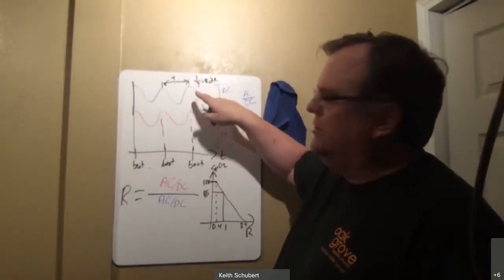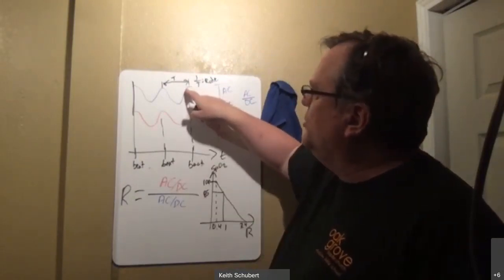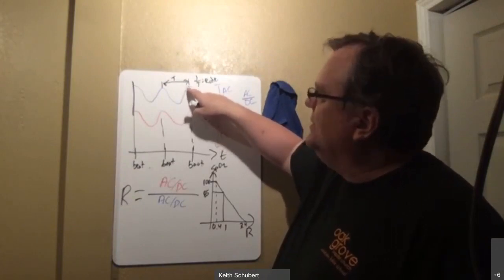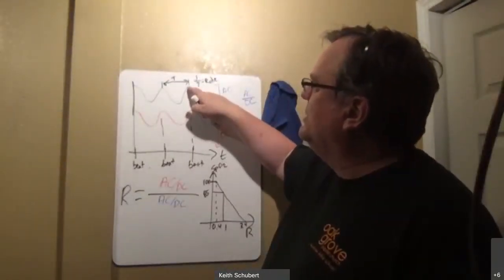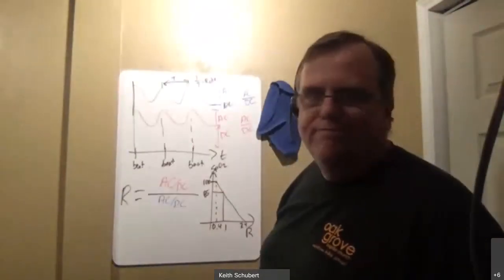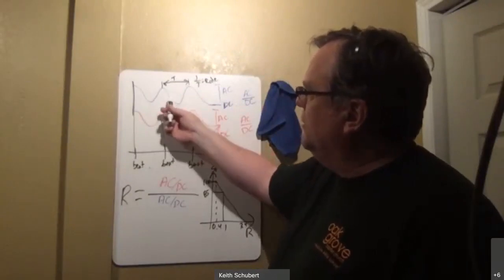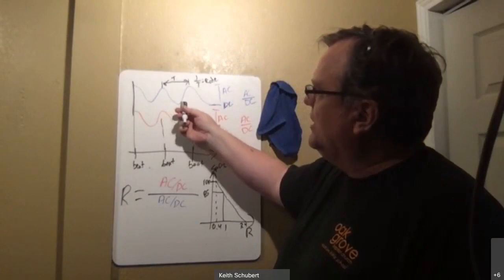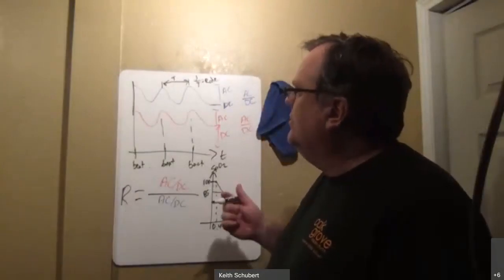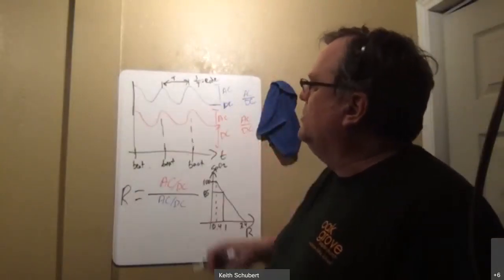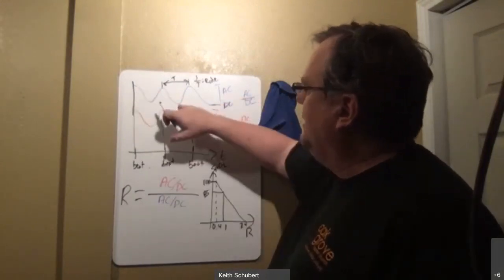all you have to do to get the max is smooth it slightly, so you put it through a slight low pass filter. Once you put it through a low pass filter, it's a little bit smoother. Then you just keep measuring as it's getting bigger and bigger and bigger. The second it gets smaller, you flash that heartbeat light, and that gives you the beats, and lets you know the maximums. The minimums you just do the other way. As you're going down, the second you go back up again, you flag the last time interval as when your minimum was hit, and you take that value. The difference between those two gives you AC, and that one gives you your DC.